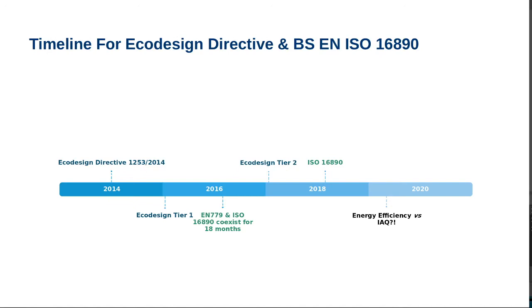It is via the cascading implementation of the new global standard ISO 16890 that the design team now has the means to confidently write a specification requisition for air filters in terms of dry pollutants for the supply of good quality air to the users of a project building.